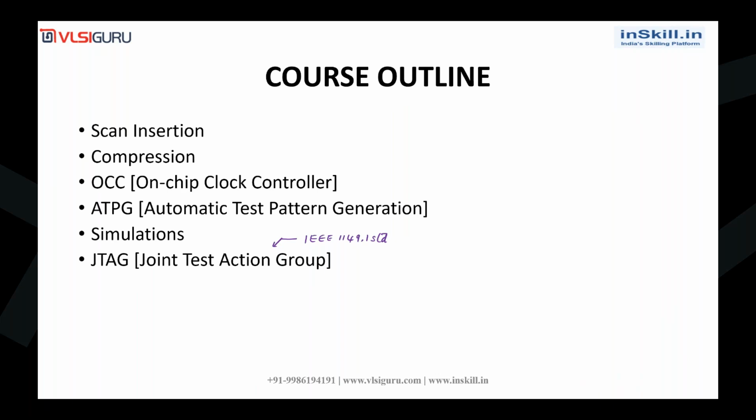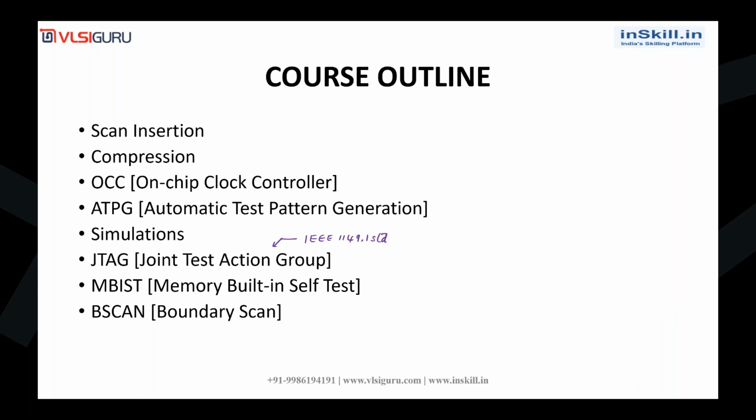And then we have MBIST, memory test. And we also have boundary scan. We will also be covering IJTAG as a part of our course. It is nothing but the IEEE 1687 standard.